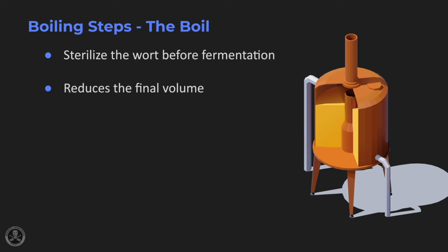Nearly every time, if not every time, a recipe is written, the boil time is included in the recipe formulation to adjust not only for the volume change, but also for the concentrations of sugars in that final volume. Now, what I mean by that is the water is going to evaporate and reduce its total amount of final volume as a liquid. However, the sugars that started in that more than we needed volume do not change. So now the concentration of sugars is higher.